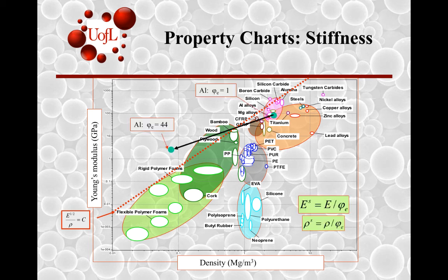Based on the information that we saw, if you can go all the way from 1 to 44 in terms of the shape efficiency factor, you can improve the effective modulus and density to the point where you can create a more effective shape in terms of minimizing mass. And the new material that was created would have modulus of the original modulus E divided by the shape efficiency factor, and the original density rho divided by the shape efficiency factor would be the density of the new material.